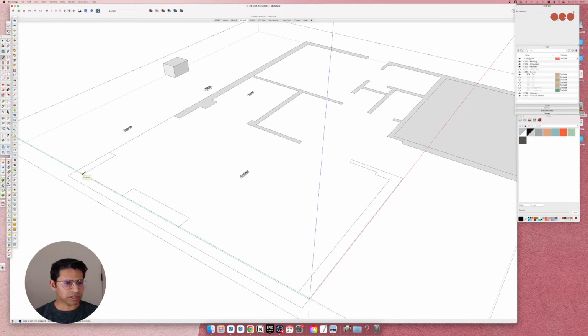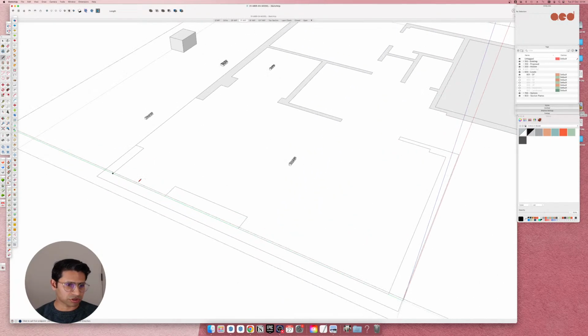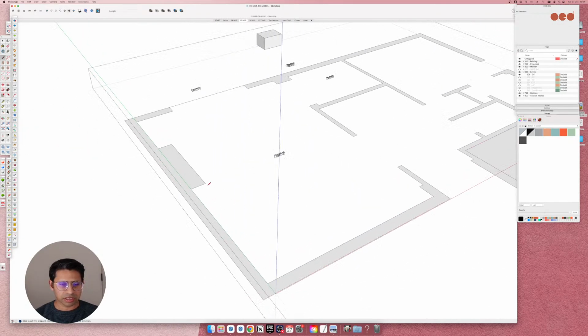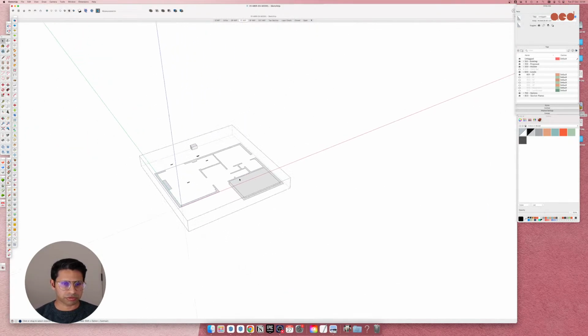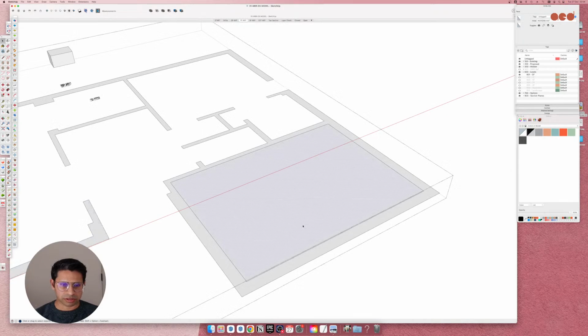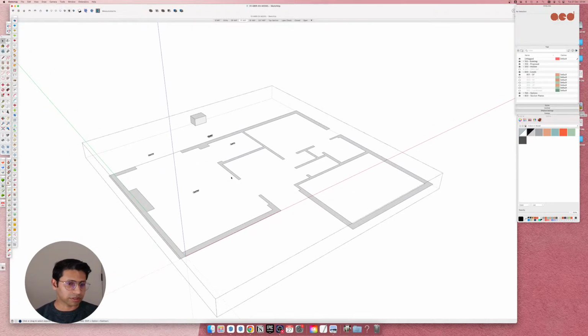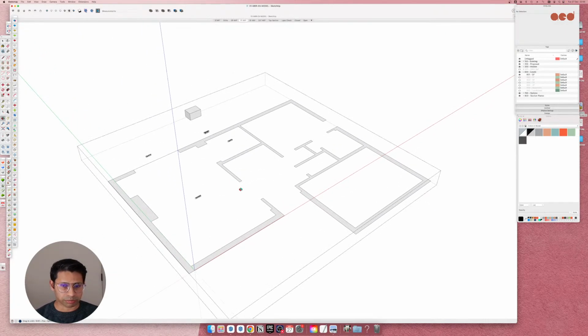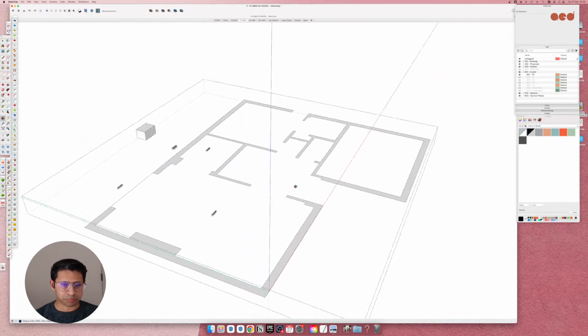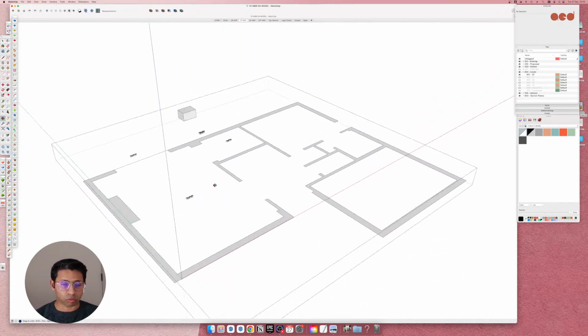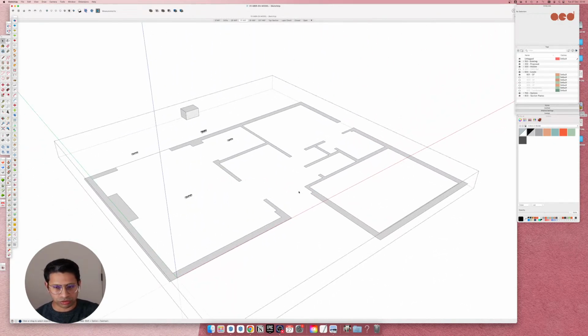So to begin with, just to close faces, you just redraw one of the edges and it starts filling in these faces. Sometimes it does an overfill that you don't need, the extra face, so I just delete that. As a starting point, I'm only modeling the walls, and we'll go through the floors, the ceiling, the staircase